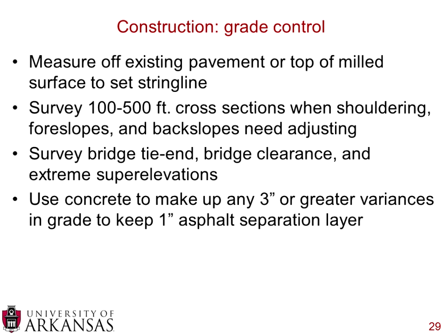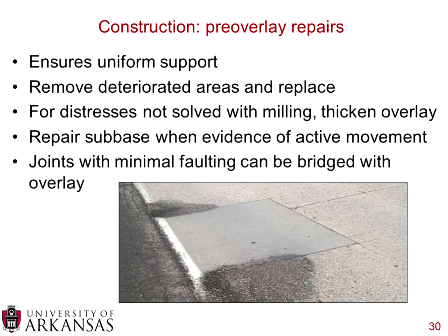And the point of this is that they're discouraging you from changing the thickness of that 1-inch separation layer, and in turn transferring that thickness variation to the concrete layers.